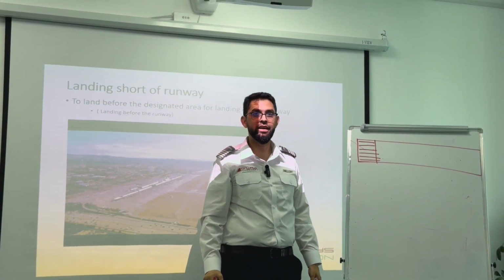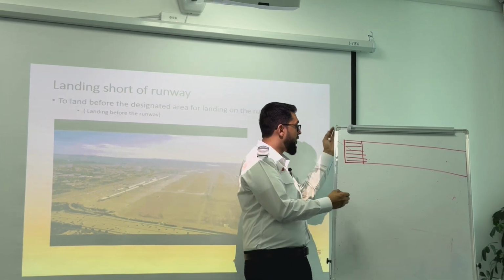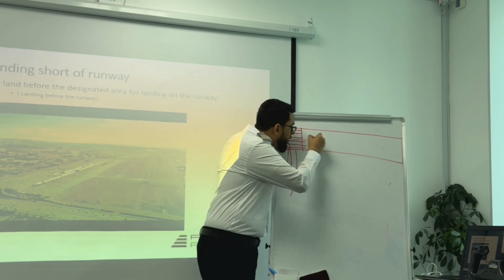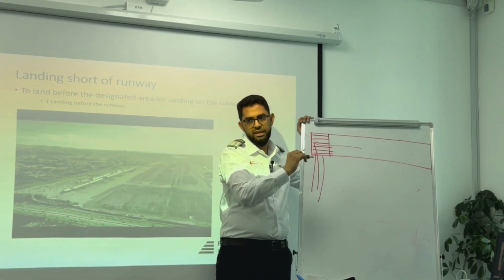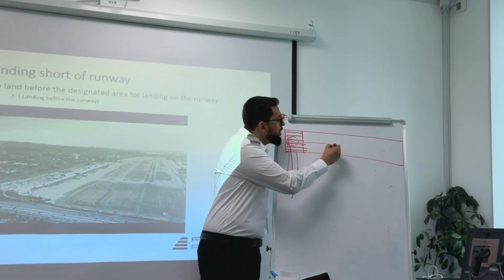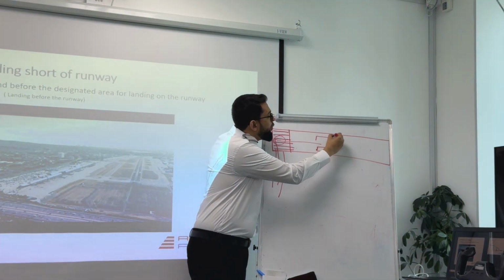You're never allowed to land on that area. It's the threshold. But guess what? If a taxiway is connecting here, sure, you can come in and start your takeoff roll using every inch of the runway. That's fine. You can't touch down here. You have to aim for the first white marker.